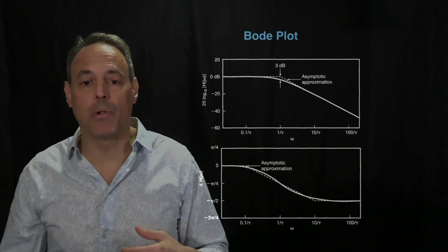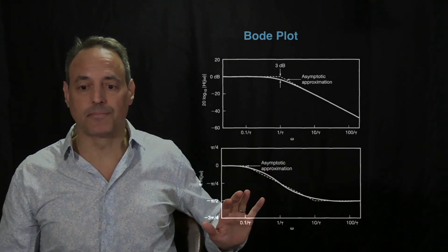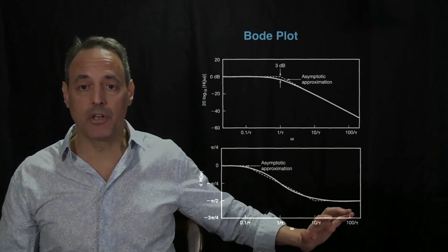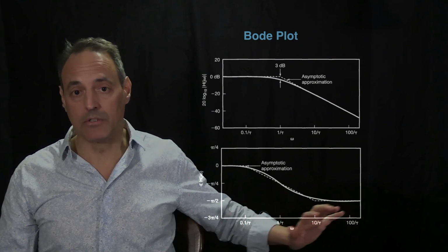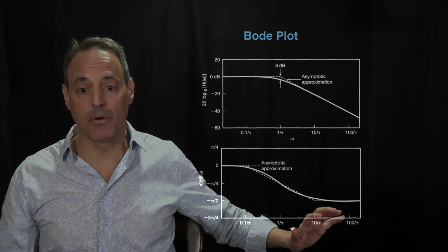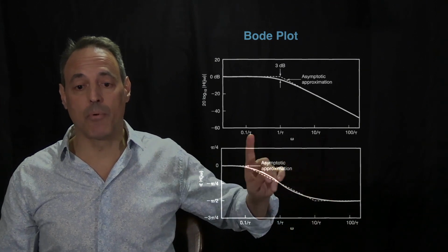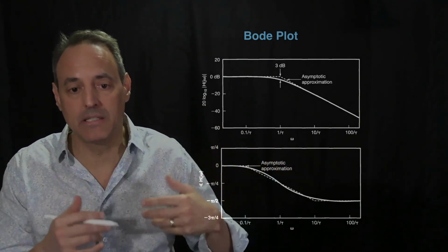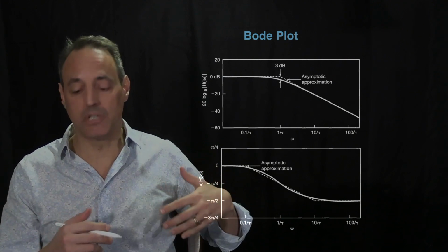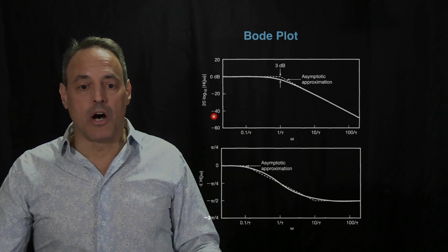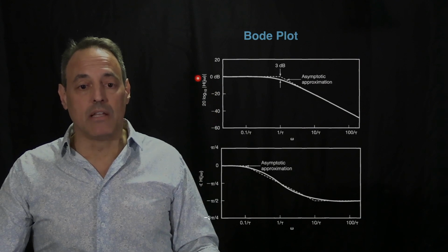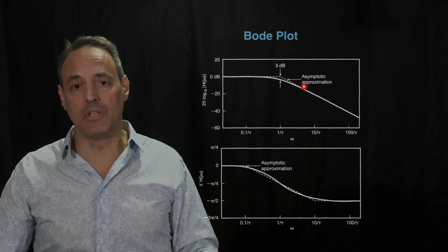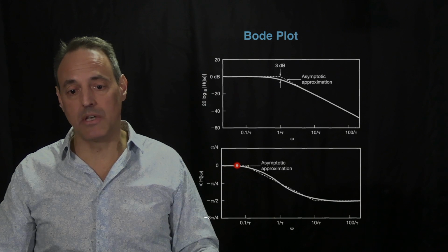And overall, the Bode plot is composed of these two pieces. So again, on the x-axis is the frequency on a log scale. We're looking at the frequency components on a log scale, and that's kind of important. What it does is it stretches things out in just the right way, the log base 10 scale, for us to look at it in a more interesting light. This is on a dB scale because we've taken the intensity of H, put it on a log scale, and multiplied by 20, and then you can see this response in its intensity, and this is the phase response of a signal.